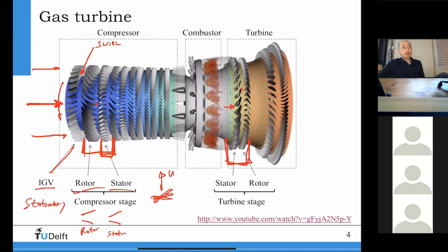Maybe electricity is not necessary at certain periods of time, because you get a lot of electricity from renewable energy sources like wind or solar. When they provide a lot of electricity, you want to reduce the load of the gas turbine so that it is not providing 100% of its capacity. And that you do with an inlet guide vane as well. So you can change the mass flow with inlet guide vanes, and then there are certain other tricks that you need to use in order to still keep the efficiency of the gas turbine high.